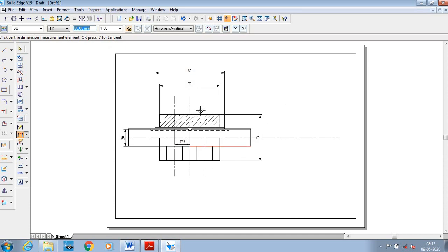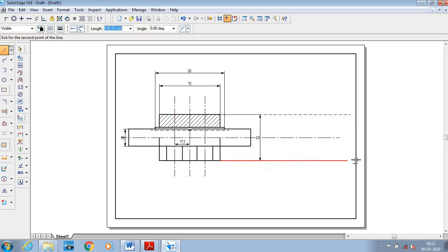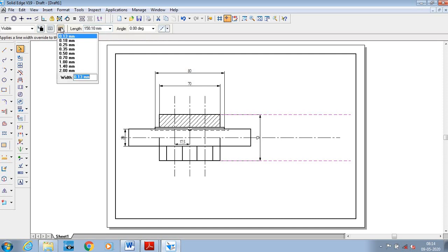Then now this is our front view, and we will draw the left side view. So that is when you look from here, so what is visible, so we will draw it here. Okay, so first, in order to draw this one, we will just draw the projection lines. Projection lines are nothing but thin lines. I will select these two lines and I will change the thickness to,